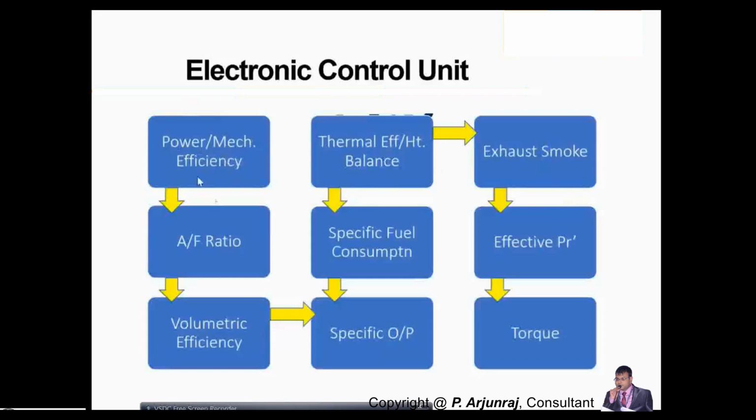When I say efficiency and the power, it is related to air fuel ratio and also volumetric efficiency. When I say thermal efficiency, it is related to the specific consumption and also the specific output. When I say volumetric efficiency, it is based on the specific output and also on the airflow, how much air is entering into the system. When I say smoke, it is based on the effective pressure and also the torque you are going to experience in an engine under different operating conditions.